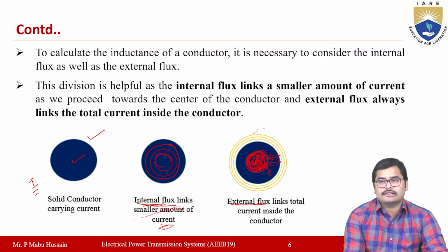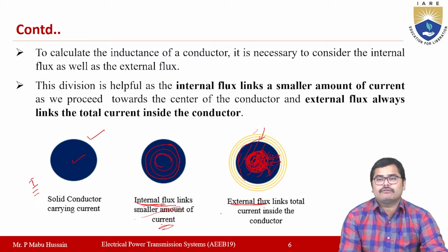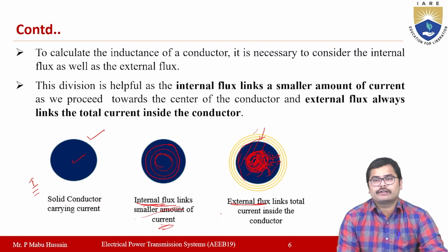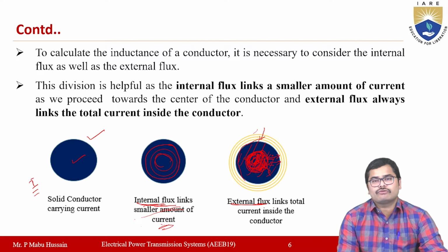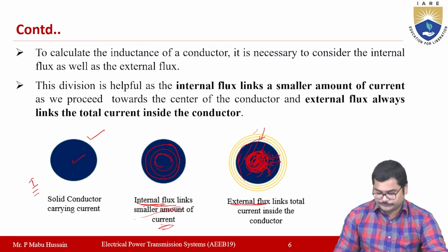Okay, but if you see the external flux here, it is outside the conductor, right? So this external flux will link the entire current which is flowing in the conductor. So always remember these 2 points: the internal flux links the smaller amount of current, while the external flux links the total current which is flowing inside the conductor.